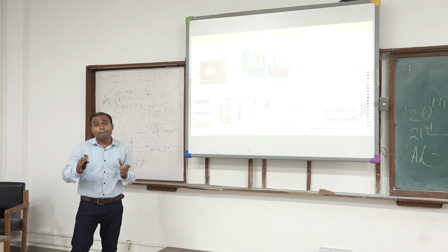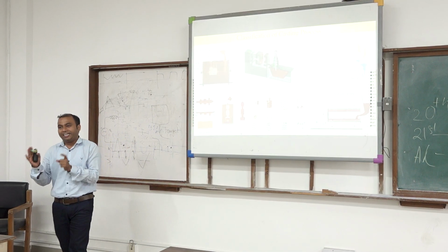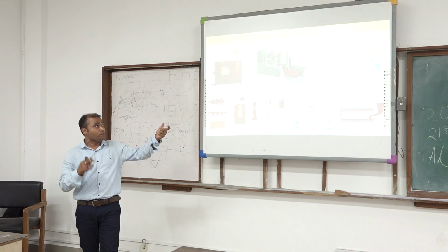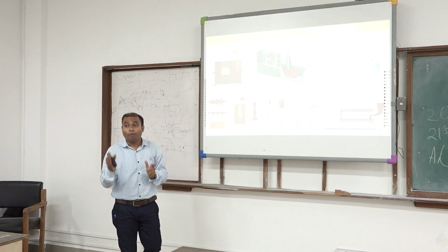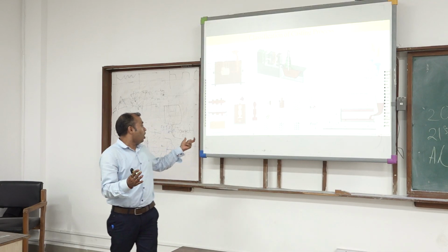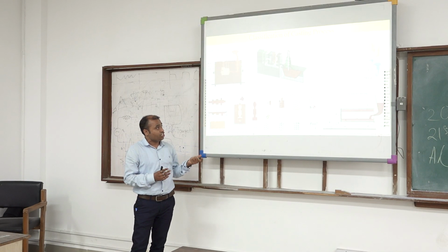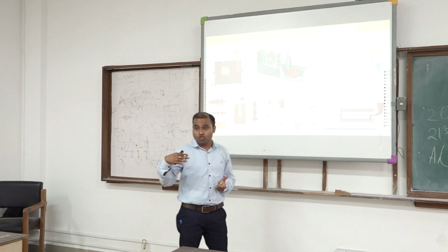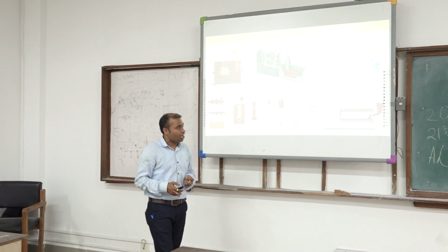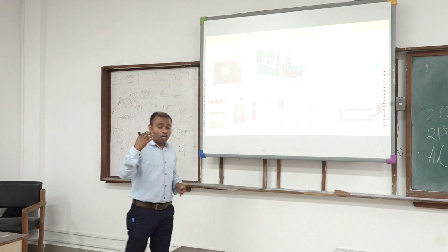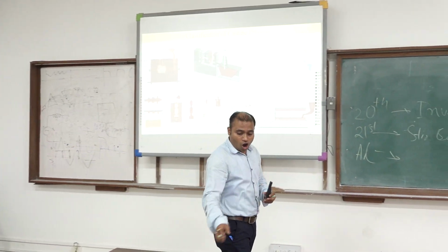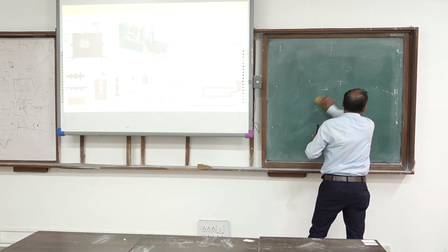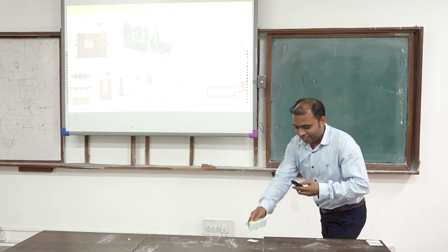Here the mold is permanent; molds made of metals are used. We have gravity die casting, where also metals are used, but the concept of low pressure gravity is being used. Now we have shell mold casting, and investment casting, which I have told is used for making jewelry products. Now centrifugal casting, where we can make hollow shaped objects with the help of the casting.